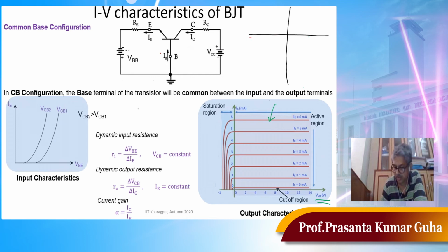So this is my reverse characteristics of the diode, where this is the reverse leakage current. We usually designate it as IS, the reverse leakage current. And this is your diode current, that is collector base current versus collector base voltage. When it is forward bias, this diode will give that exponential rise, but in the active region we are not using the forward bias, we are using the reverse bias of the collector base junction. Now this is one current, which is very tiny.